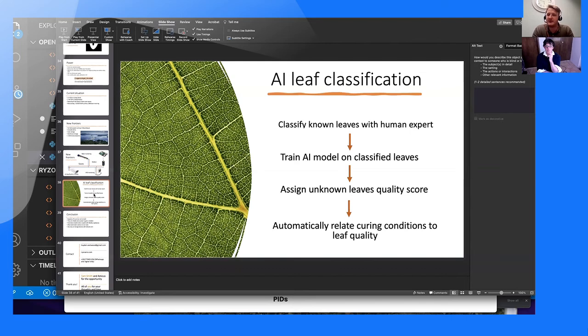Can Pis work on battery power? That's a question from Faris. Yes, they can very easily. For the fish farm, I've also got a thing sitting out in the middle of the lake, about 1 kilometer in, and that runs just off solar. Raspberry Pis only consume about 12 watts. So my setup is just a 100-watt solar panel connected to a 12-volt motorbike battery, and I then step it down to 5 volts for the Pi.